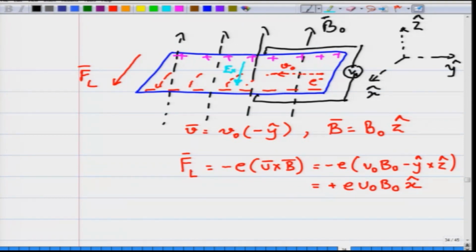This voltage which is generated is purely because when you switch on a magnetic field, the electrons get deflected and they collect along the edges of the sample, and then if you measure the voltage in the transverse direction, which is in the direction perpendicular to the flow of current, you will get a voltage drop, because there is an electric field now generated in that direction as the charges have got deflected. There is a build up of negative charge on one side and build up of positive charge on the other side. And because of this, this is the Hall effect.